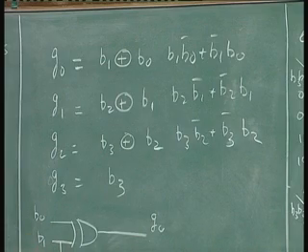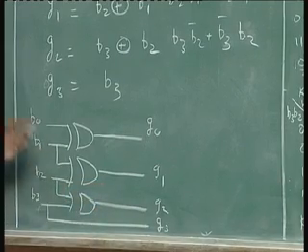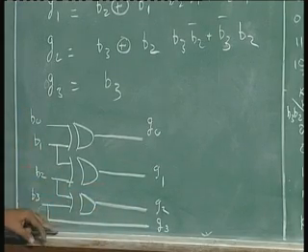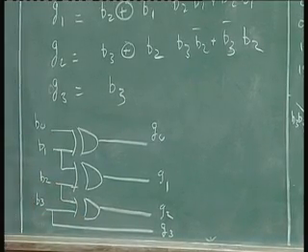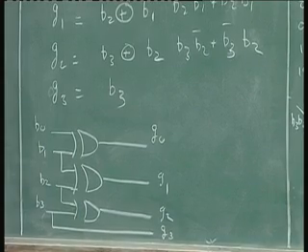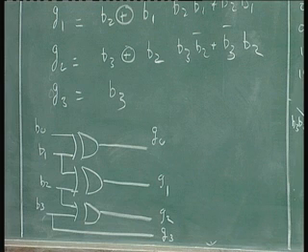So with 3 exclusive OR gates, I can get a 4-bit binary code into 4-bit gray code. The same logic. If it is 5 bits, one more exclusive OR, B3, B4. It goes on. So 7-bit binary code if you have, you can get 7-bit gray code by using 6 exclusive OR gates. It's a very simple, elegant circuit, practically used also. As I said, many times people want to convert the binary code to gray code before doing the processing for all the switching activity that I told you, and then get back the binary. So this is a very elegant circuit, commonly used circuit.